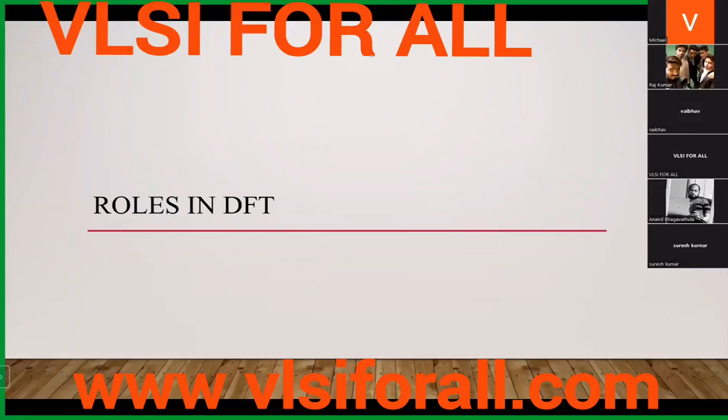We reset through asynchronous reset so that there should not be an unknown value, but that is not important actually. Even if we have an unknown value, we clean that space with our known values. So in DFT, generally we have asynchronous reset. We don't have synchronous resets.